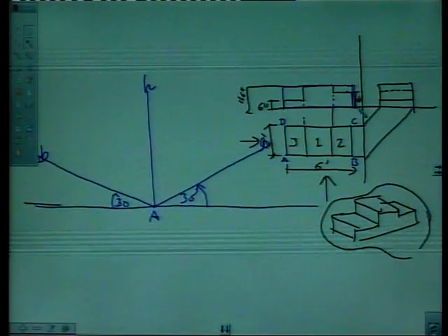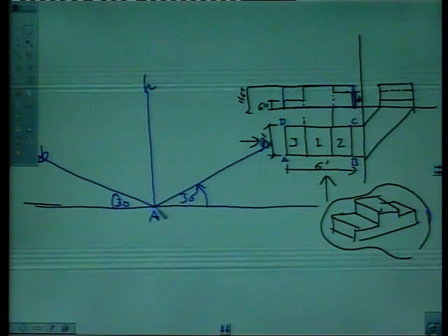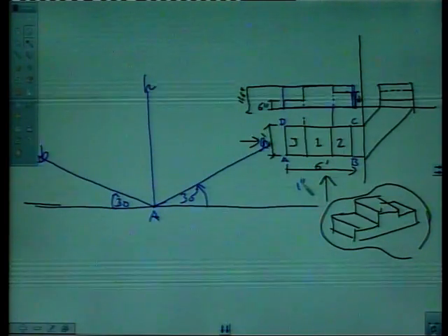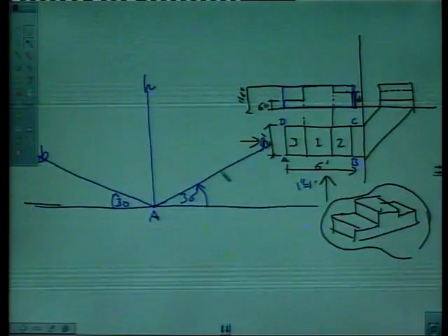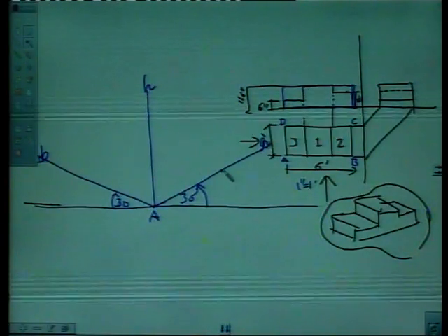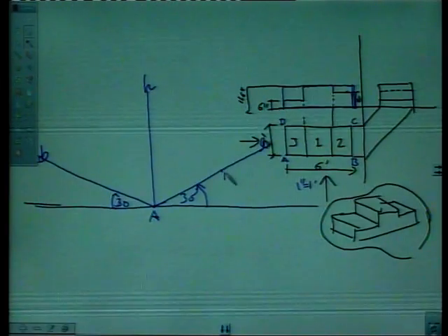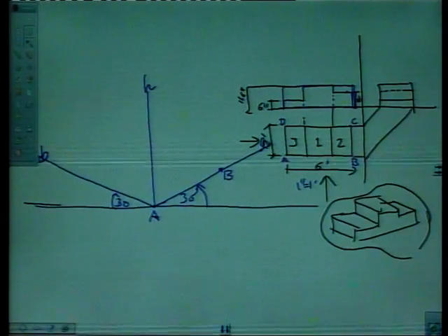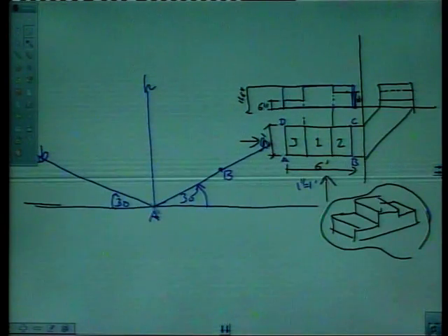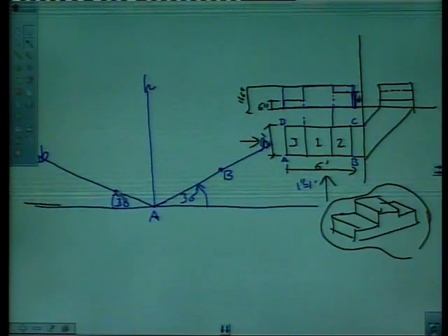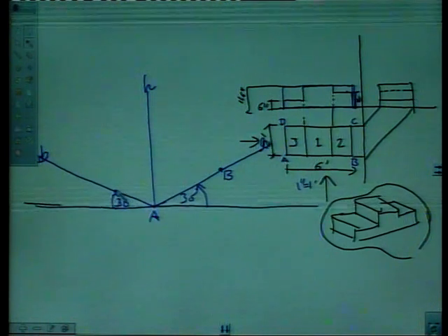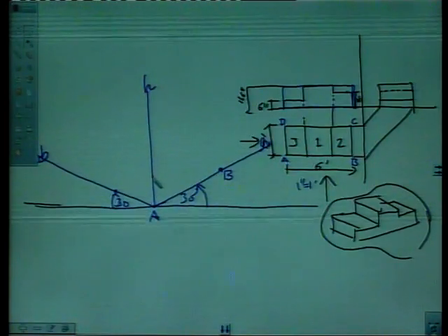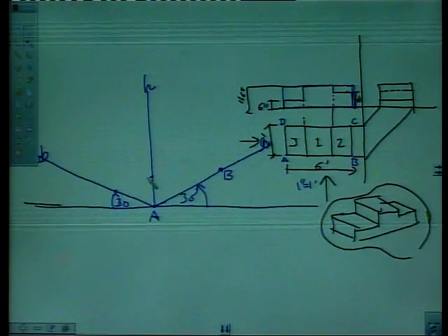So the size of the cuboid will be length 6 feet, mark 6 feet to the scale, right. Say we are using a 1 inch scale, 1 inch is equal to 1 feet. So mark 6 inch here, right. Then this will represent point B, the maximum length of the victory stand. Width of the victory stand is say 2 feet, mark 2 feet here as per scale, right. And height is 1 feet 6 inches. So mark 1 feet 6 inches to the scale here, right.